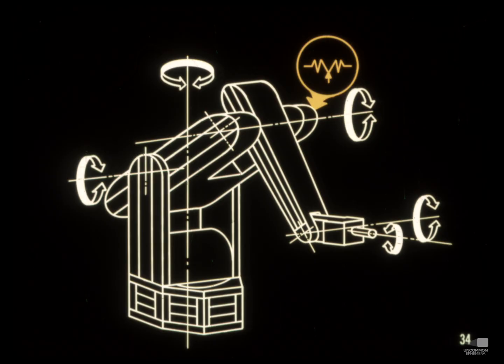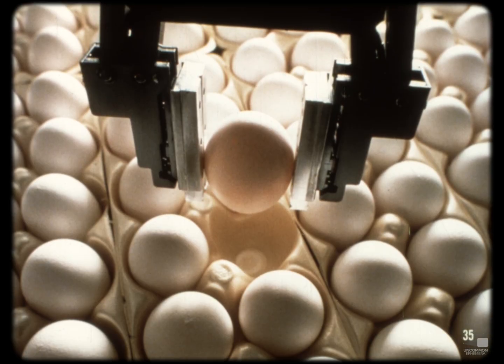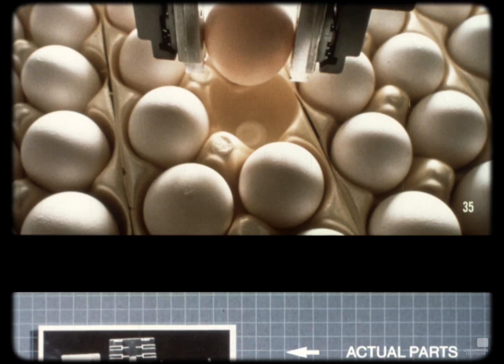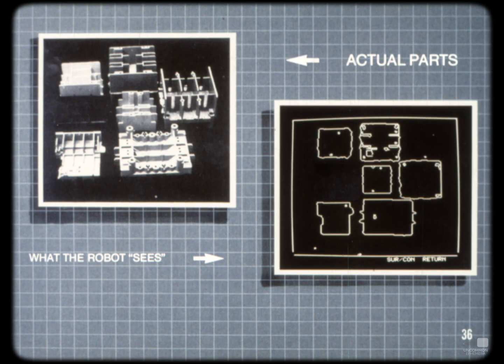electronic circuitry. Strain gauges, or load cells, mounted in the robot's gripper can be related to an electronic circuit so that the gripping pressure of the fingers can be controlled to allow delicate materials to be handled by a robot without damage. A robot equipped with video camera sight capability can see if the material to be handled is oriented properly for the present position of the end effector. This video information enables the controlling computer to provide the proper control signals to reorient the hand if needed.